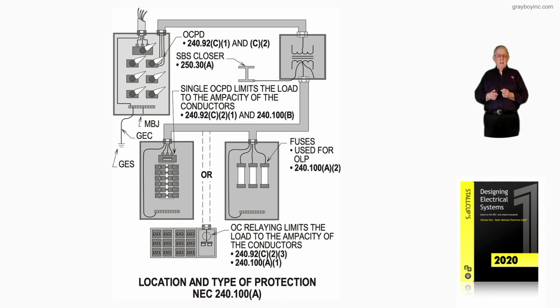So this Figure 9-46C is illustrating the three methods of design using circuit breakers, fuses, or relays in accordance with 240.100 and 240.101.